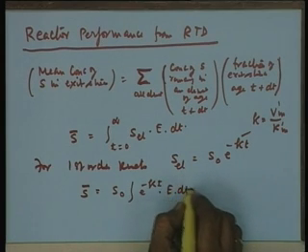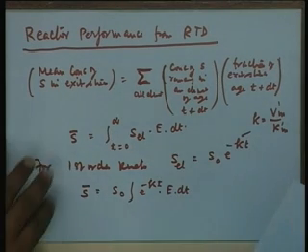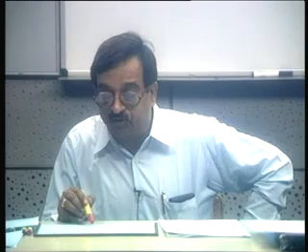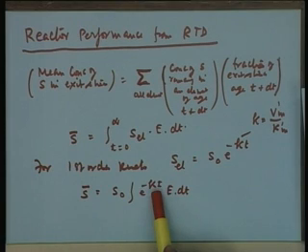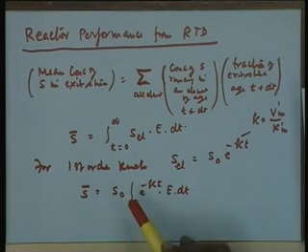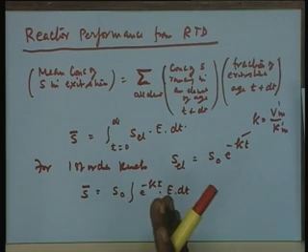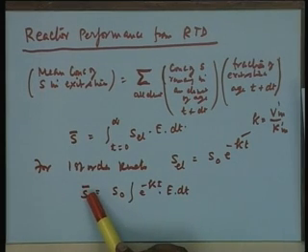Essentially what it amounts to is that if you have a residence time distribution for any real reactor in the form of E dt, and if you also have the first order rate constant, which can be evaluated for an enzyme reaction, you can sum this over all the fractions of the exit stream which has been collected, and you will get the mean substrate concentration in the exit stream.